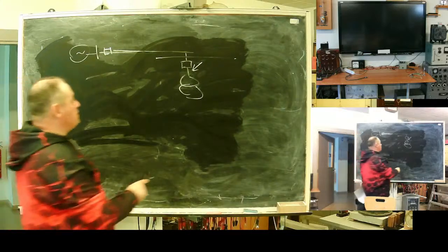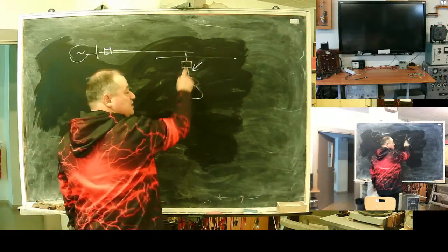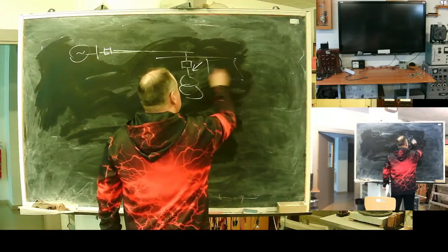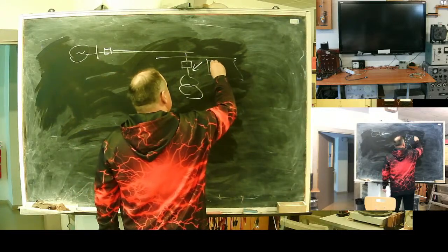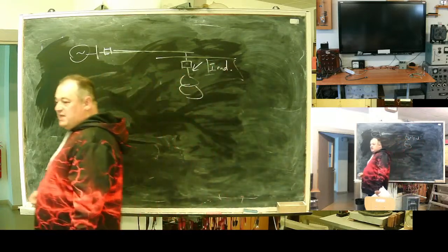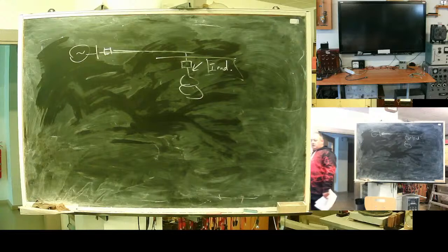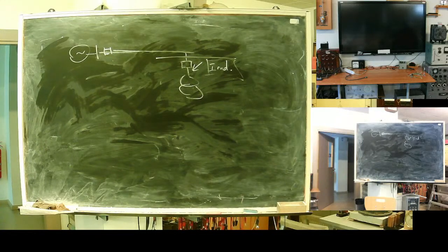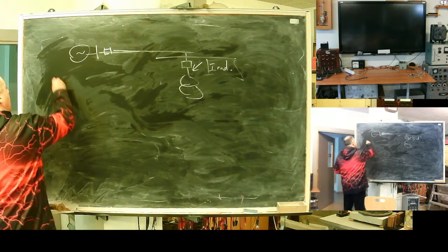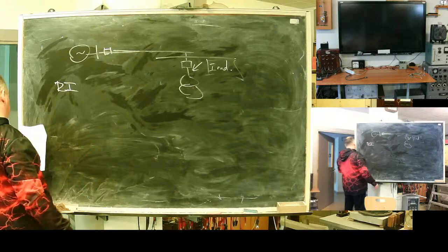You cannot ask them to change protection here. They have an induction type of relay, so you need to align. The customer may listen to you, may not. If the customer does not listen, use the RI type of characteristic.